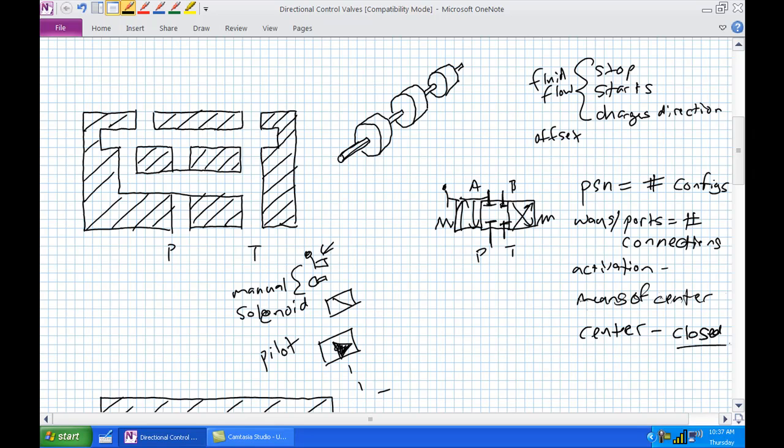There's a number of different types of center positions, and we're going to go back into some of the other ones that we may have not seen at this point, though. But right now, just pretend that we're dealing with the closed center position, which we are. Okay, so now let's go back to our discussion about our spool and how this thing does exactly what our schematic says. So let's put our pretend spool in here. So it's a closed center position. I'm going to go ahead and put that in. And there is our spool in the closed center position.